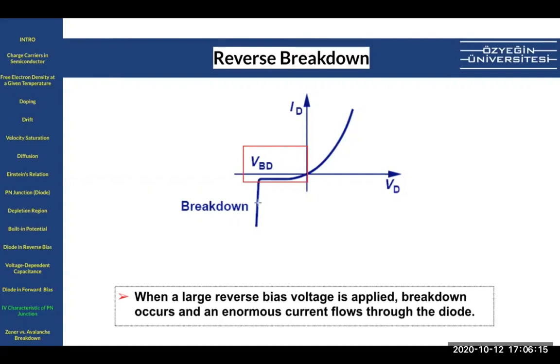But then at some point, a breakdown occurs, and this happens at a very high minus voltage. That is a phenomenon in diodes. We won't really get into so many details why, but just know that this phenomenon exists in diodes: when you apply a very, very high reverse voltage, the depletion region gets bigger and bigger, and it eventually breaks down because the diode has a certain length, right?